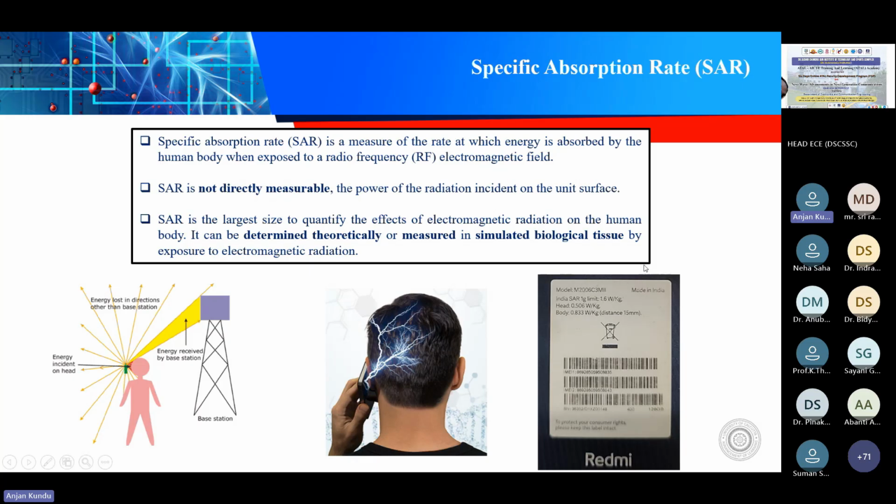That's why every mobile carries a sticker at its back mentioning the SAR limit. And whenever we are trying to develop a biosensor, particularly an on-body or in-body biosensor, we definitely have to calculate the SAR of that sensor and design that sensor accordingly so that it obeys this 1 gram limit. There is a 2 gram limit also. For research, it is the 2 gram limit, and for practical products, it is the 1 gram limit. There are two limitations actually for SAR in India. Not only in India, there are limitations all over the world. These figures depict only India.